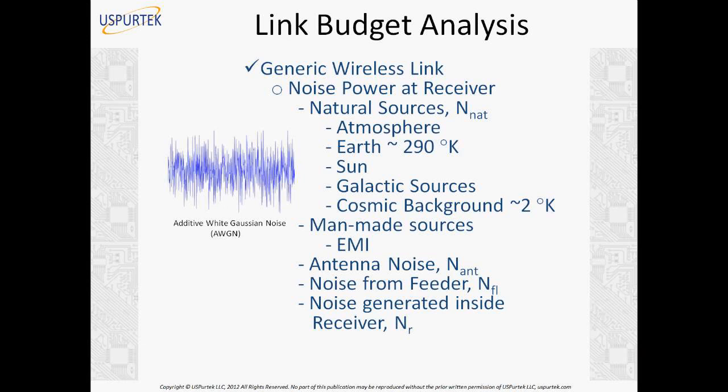Well, as we'll see later also, there is a specification on the receiver side called sensitivity. It's a specific dB value, how much signal level is good for the device for getting full bandwidth. It's always defined in the receiver specifications. If your signal level is above that sensitivity level, then definitely you are getting full bandwidth.